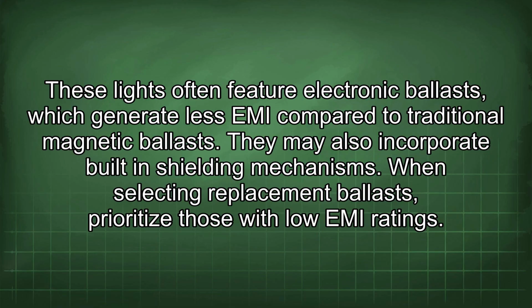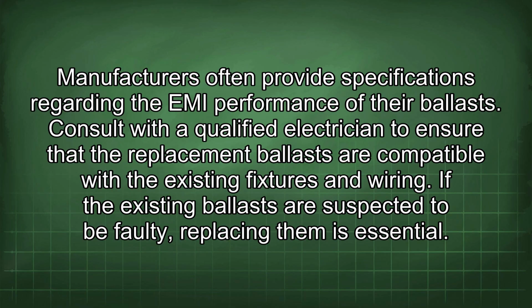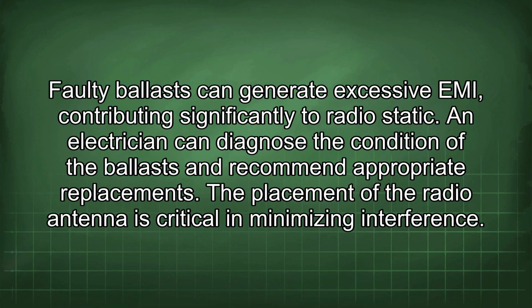When selecting replacement ballasts, prioritize those with low EMI ratings. Manufacturers often provide specifications regarding the EMI performance of their ballasts. Consult with a qualified electrician to ensure that the replacement ballasts are compatible with the existing fixtures and wiring. If the existing ballasts are suspected to be faulty, replacing them is essential. Faulty ballasts can generate excessive EMI, contributing significantly to radio static. An electrician can diagnose the condition of the ballasts and recommend appropriate replacements.